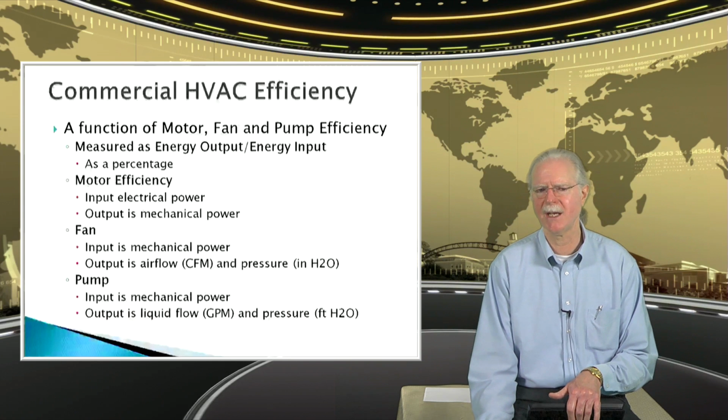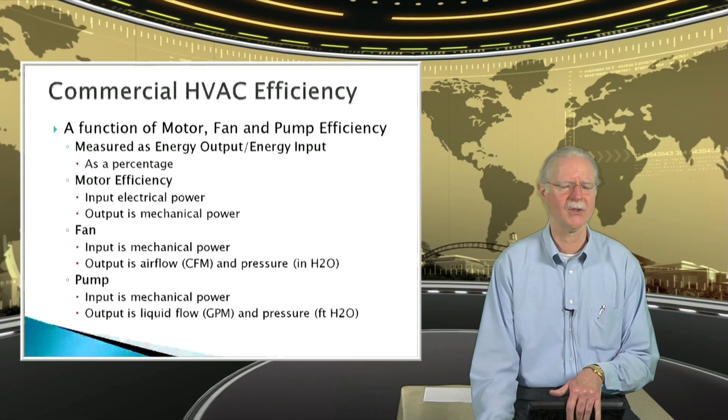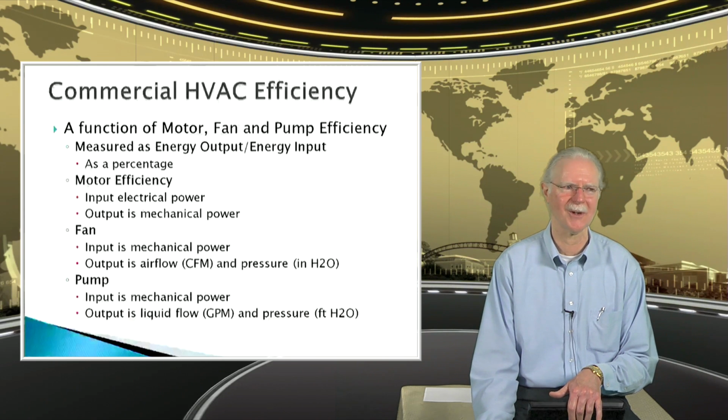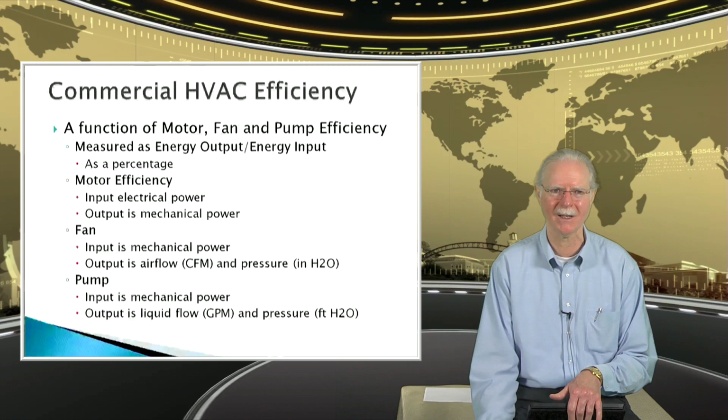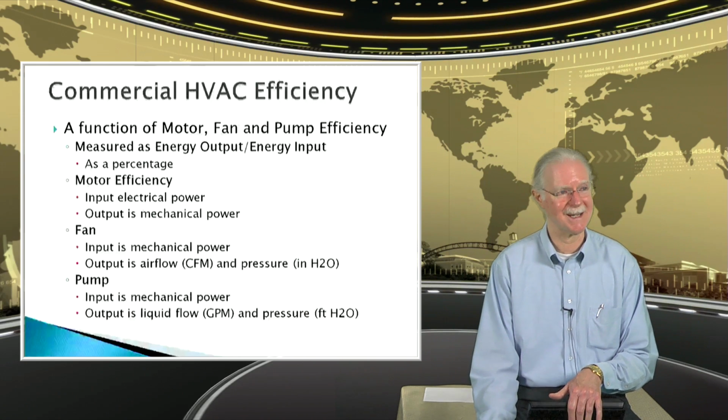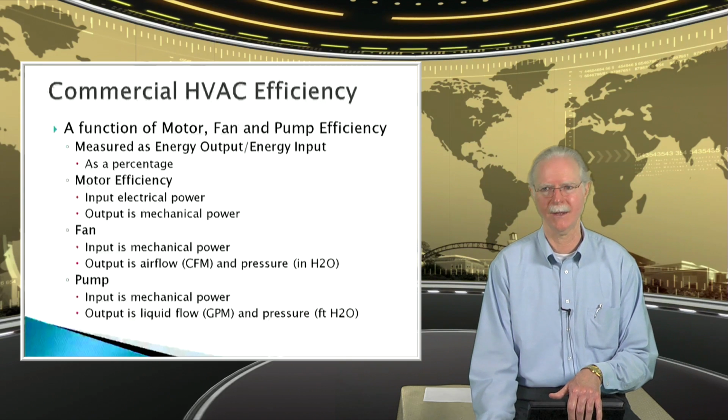In a residential setting, if you're doing a retrofit after 20 years, the heating and cooling system is probably in a situation where it's easy to replace. The first cost isn't that high, and the systems are reaching the end of their life expectancy anyway. Commercial buildings aren't quite so excited about replacing equipment because the investments are large. Instead of $4,000 or $5,000 investment, they're talking about $40,000 or $50,000 investment per rooftop unit, and they may have 6 of them. So they're not going to get real excited about replacing everything.